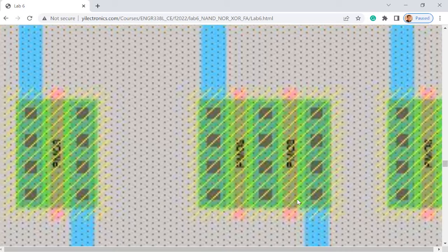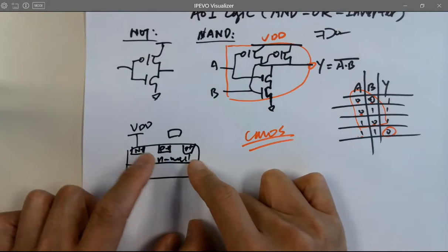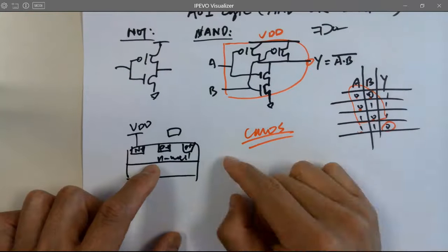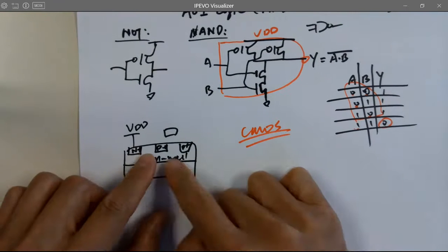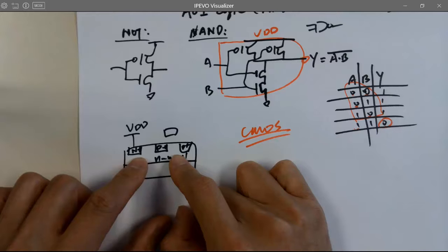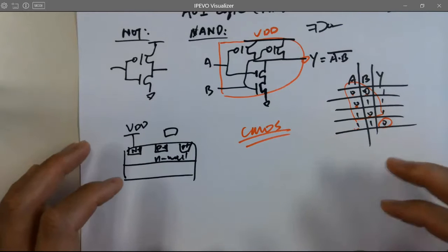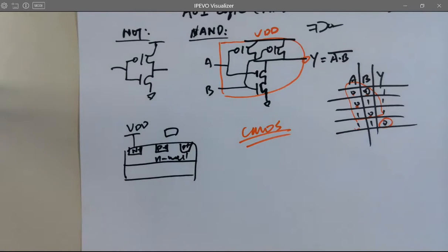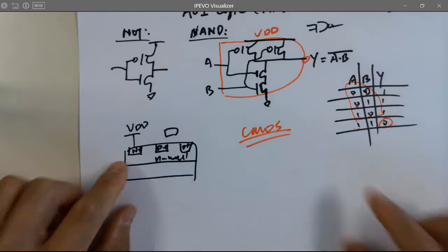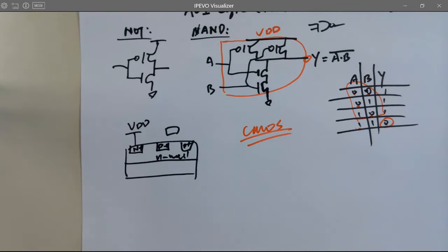But does that make sense? So the N plus is N plus. So the dots are N plus, right? It's N well. They are both in the N well. That's why it's N plus. They are both N material. That's why you want to put up one well for the PMOSs and the tap or the contact, body contact, putting one well.